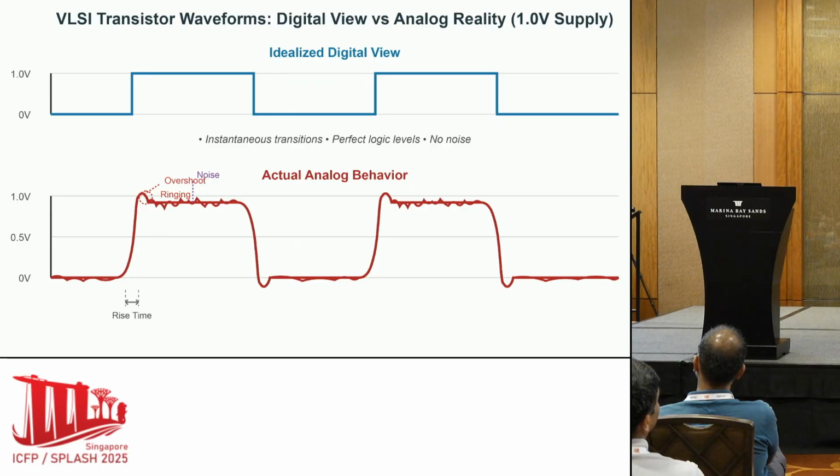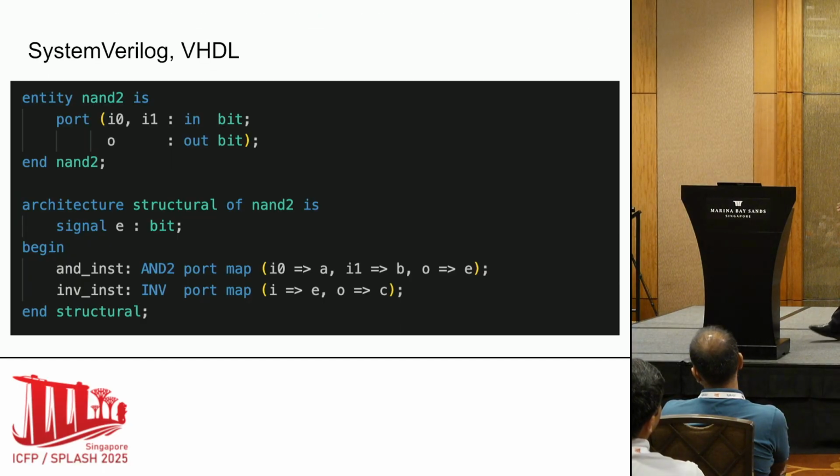And so when we think of ones and zeros, really under the scene, it takes time for a signal to rise from 0 to 1 and 1 to 0, and it isn't totally flat. It's all kinds of noise and so on. So when we stretch systems to a limit, let's say we try and toggle too many transistors at the same time, even though the circuit should work in the digital domain, it starts to fail in the electrical domain. Abstractions are wonderful, but we should always understand the limits of our abstractions.